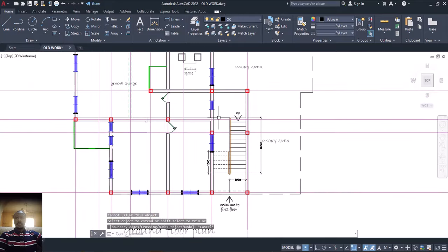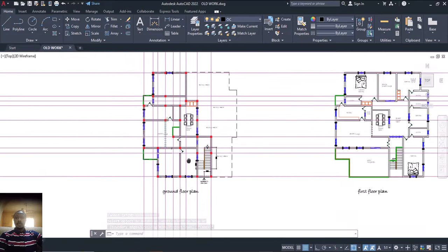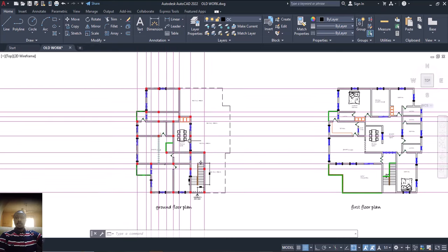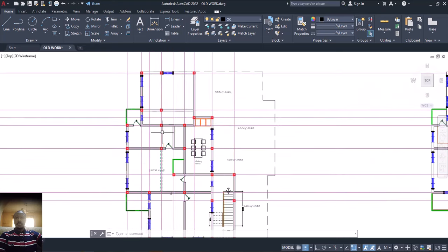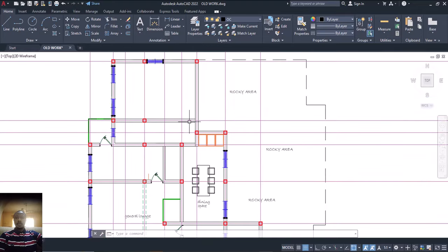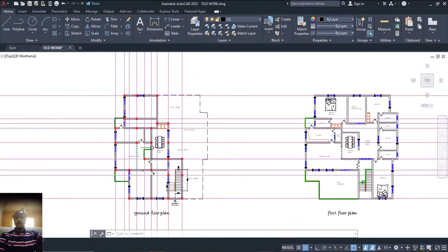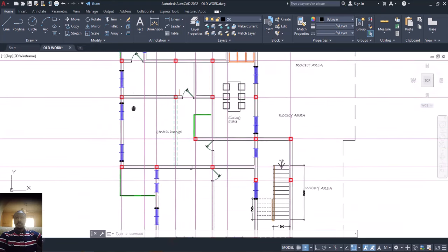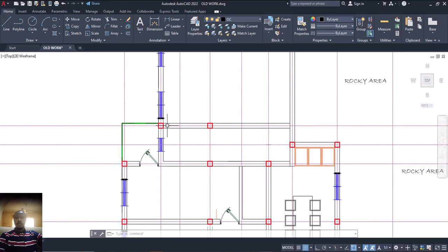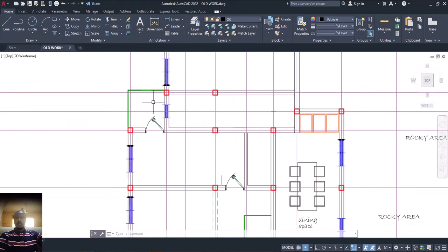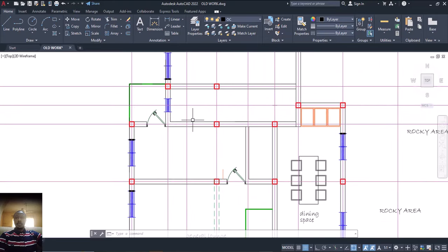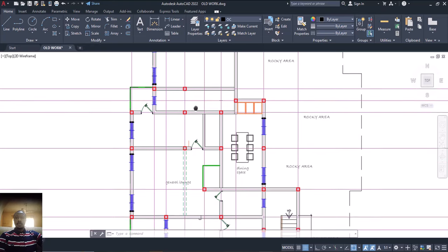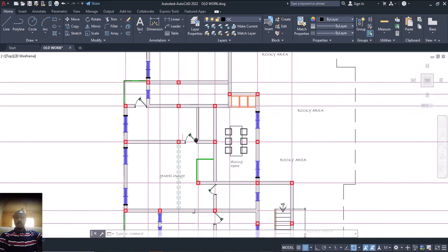Then you know that this is our staircase, isn't it? So for this particular place now, we are done. We are done with this particular ground floor. Now don't forget this one is a cantilever. If you like, we can have a projected beam here, which is our cantilever beam, to support this all the time. That is if you want, or you make it entire pure slab without the support of beams. That is that.